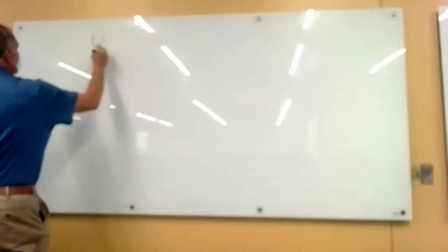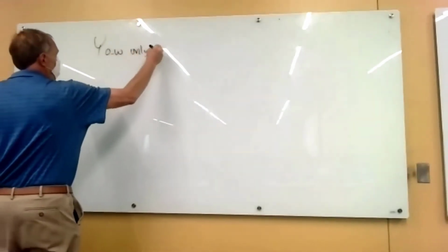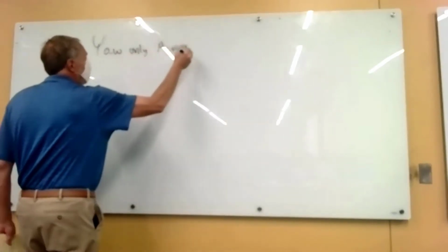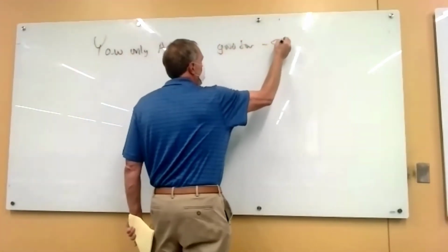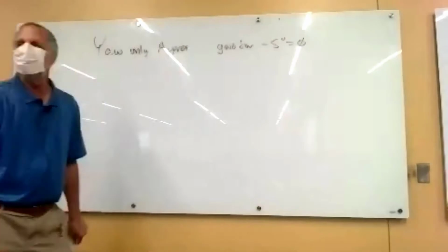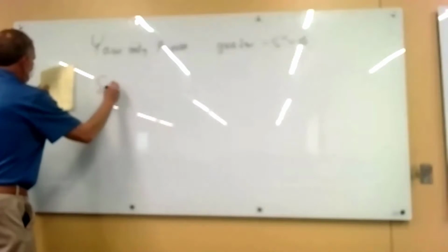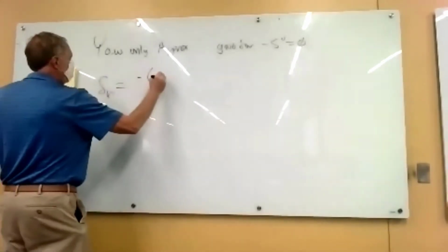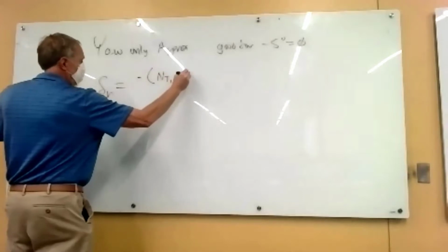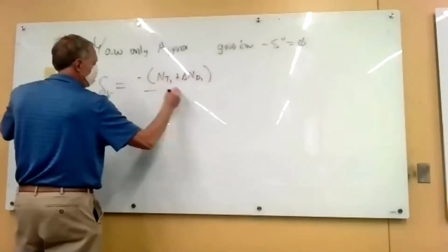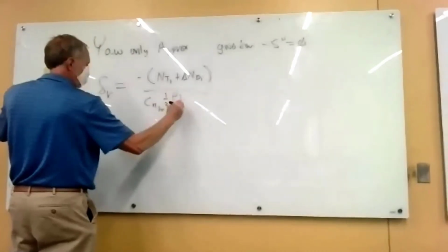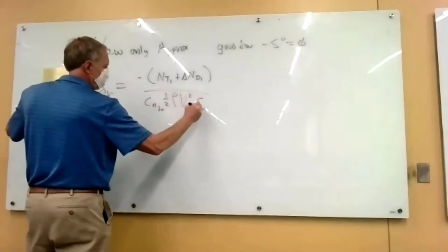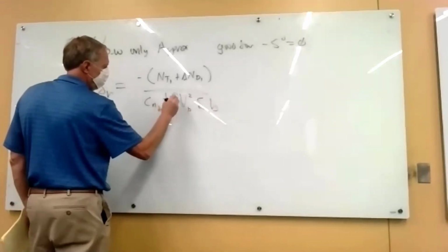So this is the yaw-only approximation, which we found out is good for about minus 5 degrees bank. So if we allow the airplane to bank a little bit, it helps out. And then the rudder can be calculated from this approximation. Again, for any airspeed, right?